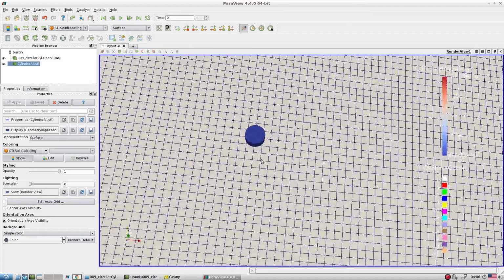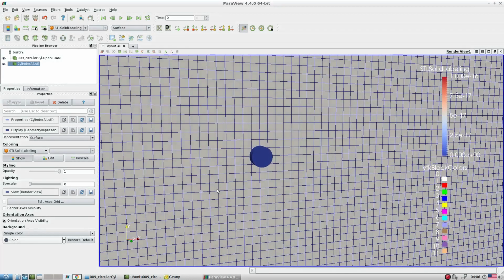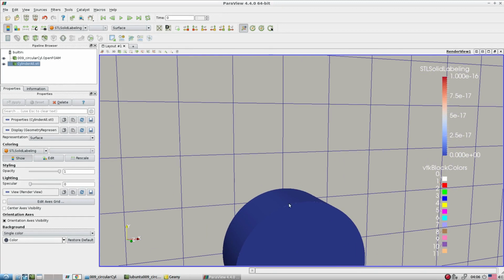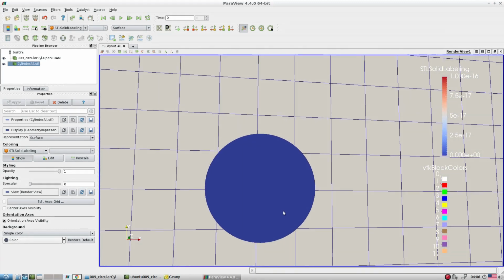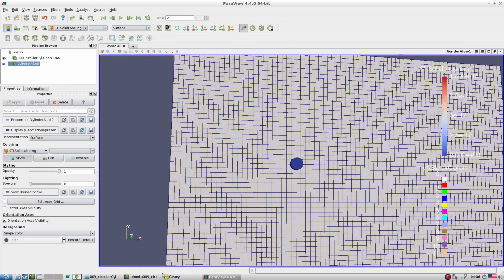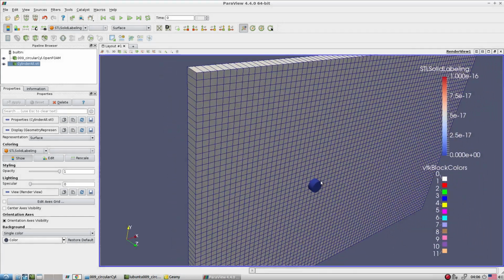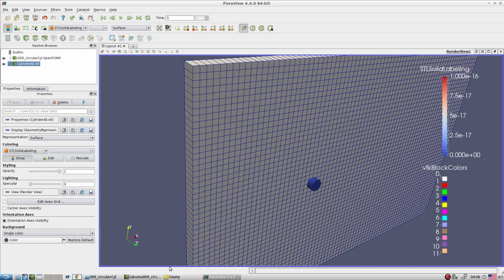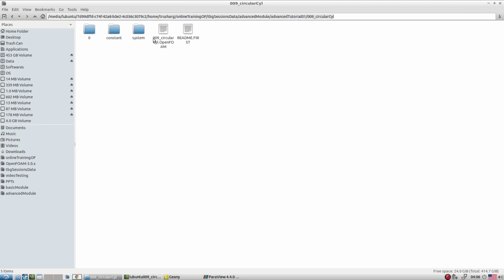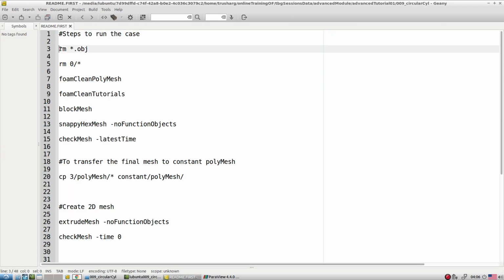That is our starting point, and make sure we have regular aspect ratio cells near the surfaces, and at least one of the cells is supposed to cut the surface. That is the requirement. So as usual, first create the entire mesh. There is no difference in creating the mesh; we create it with all our regular commands. So let's generate the first mesh and see how it looks.